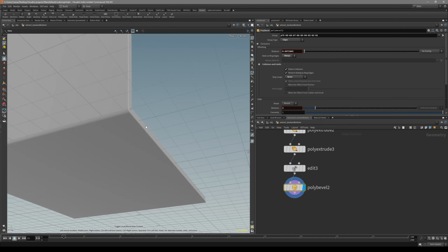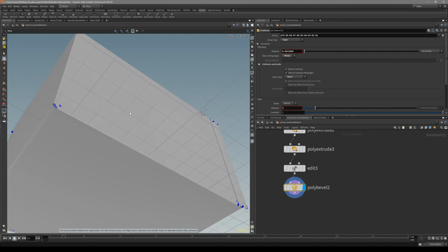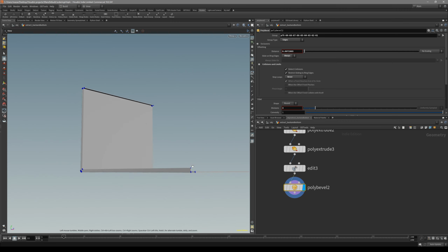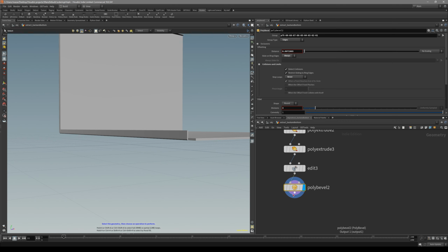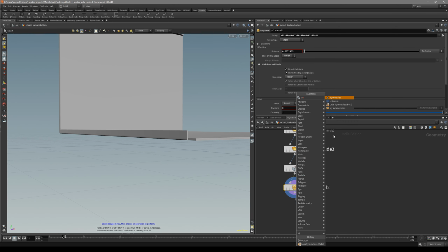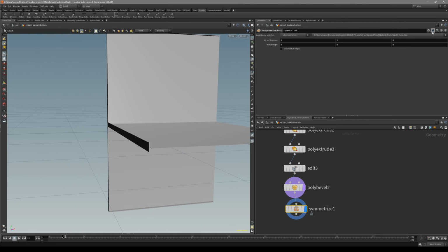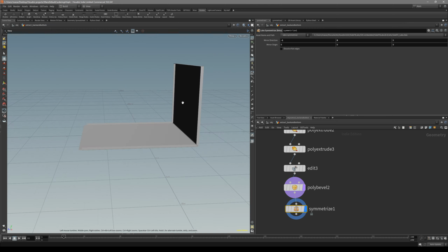So first of all, we're going to have to move it around a little bit. But for that, since now we're basically happy with our shape, let's just symmetrize it. Let's put down the LAB Symmetrize node. So now we want to symmetrize on X again. So mirror X. Now we have our symmetrized geometry.